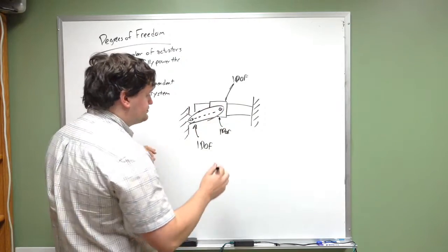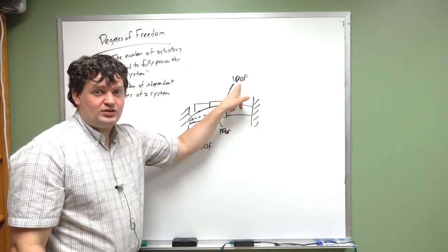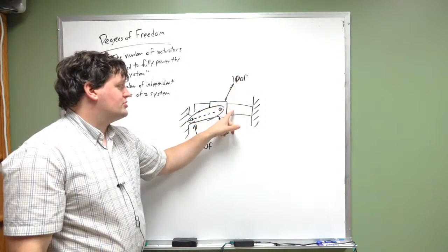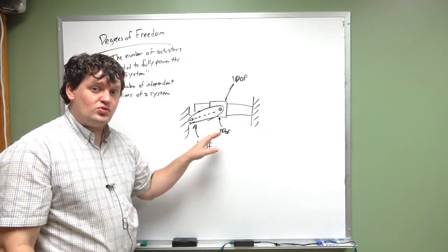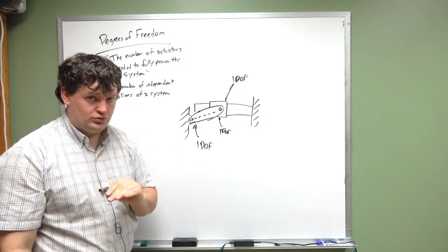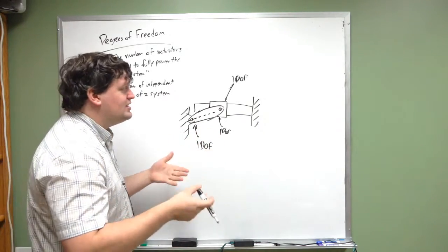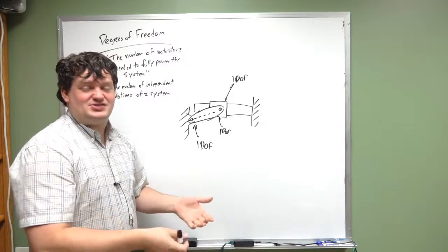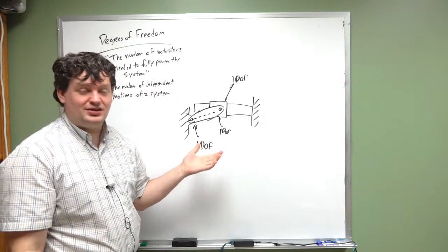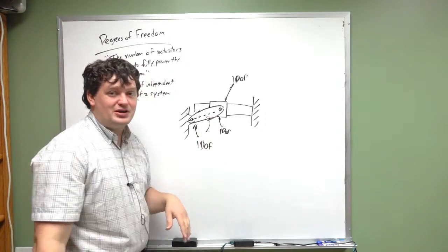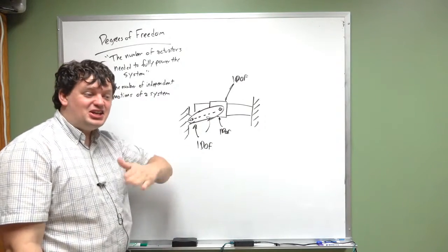However, this component back here is restricted from moving in the y direction because of the 1 degree of freedom joint on this rail. This system, as drawn right here, cannot move. It can't move. It is fully constrained. It's stuck. You try to put this in motion, it won't move. It won't do anything. You throw an actuator on here, throw a motor on here, that motor's going to burn out real quick because it's not going to do anything.